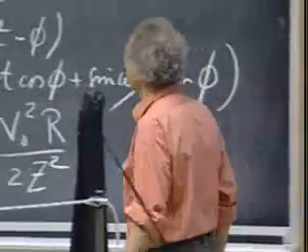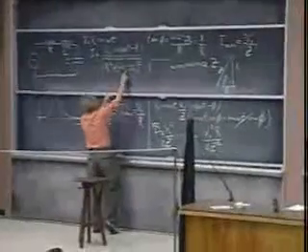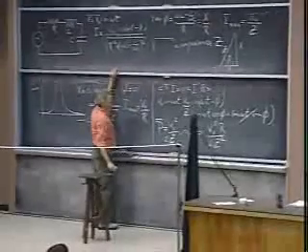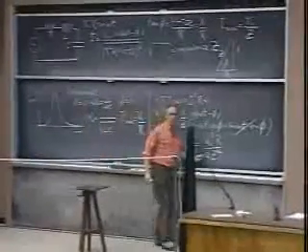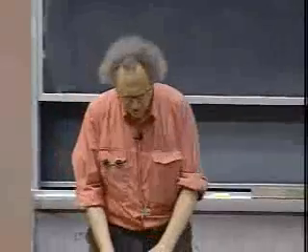At any other frequency than omega 0, Z would always be larger than R. You see that immediately here, and so that means that the average power would always be lower. So it's only at resonance that you generate the highest power possible.